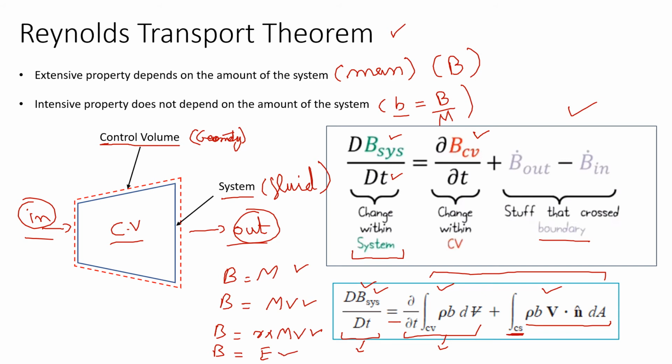And this right here gives us our energy equation that we use to find the energy required to run a certain pump, or the energy that we can extract from a certain turbine. So this was very important for us, and we use that for different conservation principles that we are going to see in the next slides.